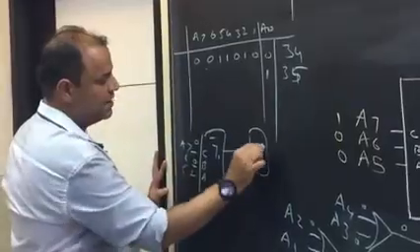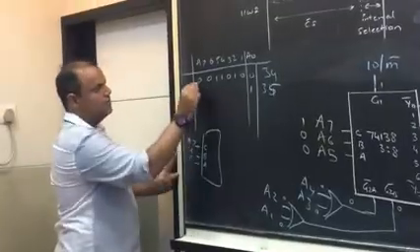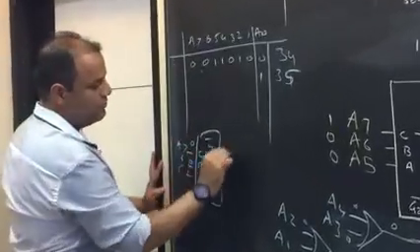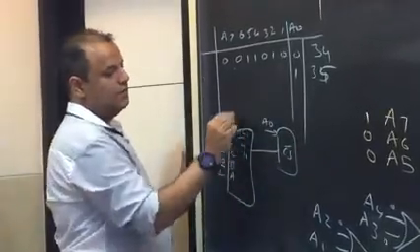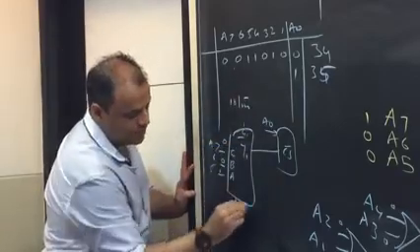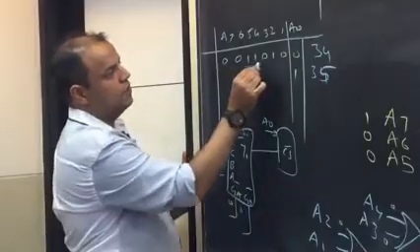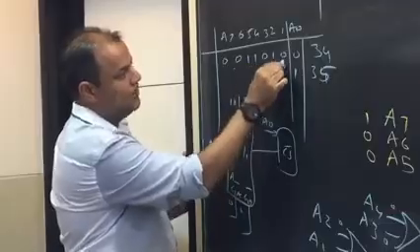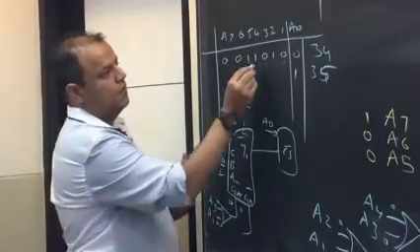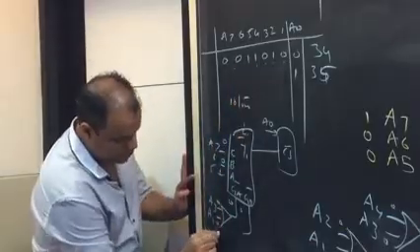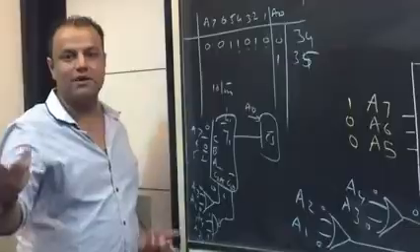Keeping everything else the same, now this is your decoder, C B A. The lines you will take are A7, A6, A5. So your combination will be 001. Your output will be Y1 going into chip select. A0 has already gone inside the chip, A5, A6, A7 are here. G1 will be connected with IO/M bar, and G2A bar, G2B bar both want a 0. What is remaining? A4, A3, A2, A1. A3 and A1 are 0, so A3, A1, both of them are 0. OR gate. A4 and A2 are 1. NAND gate will give a 0 only when both of them are 1. Please tell me, did you understand?